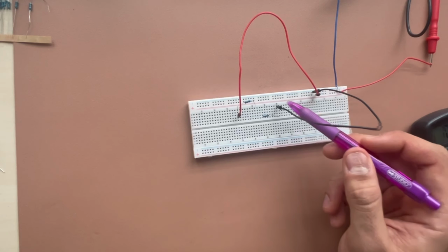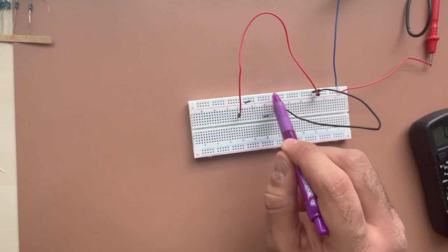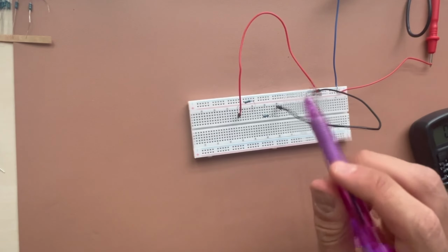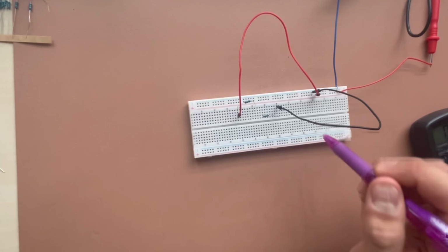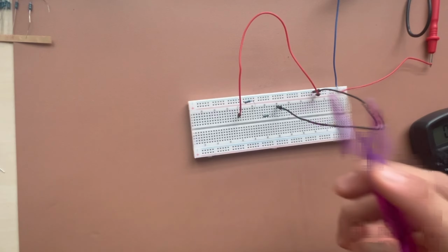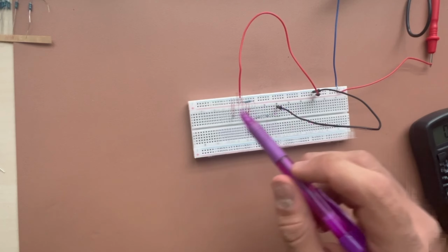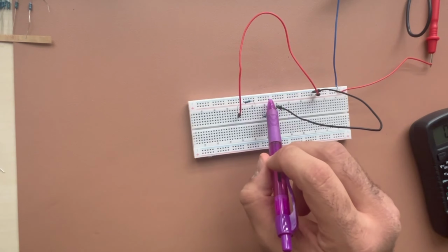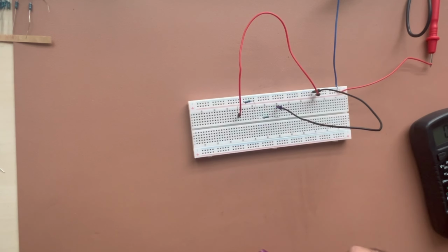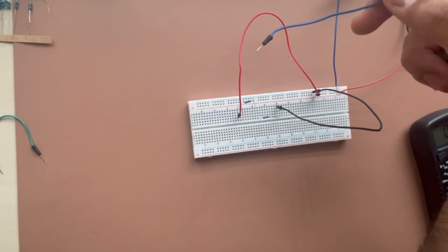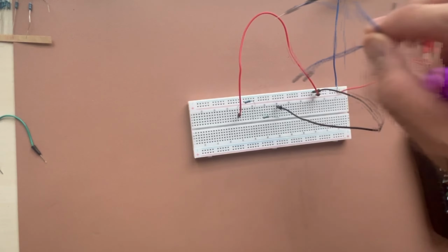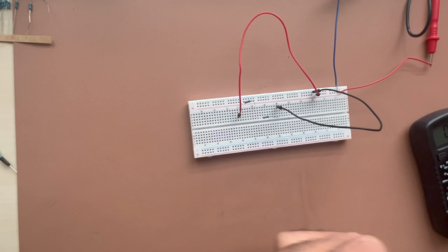Another thing that you have to know is that at some points between these two sections, the middle rows are not connected to each other, but since we are not using that, we don't care. But just in case you're using those points too, make sure that you use one jumper between here and here. A normal jumper like this would do the job. Connect it from this point to this point, and you make sure that all of those are connected to each other.